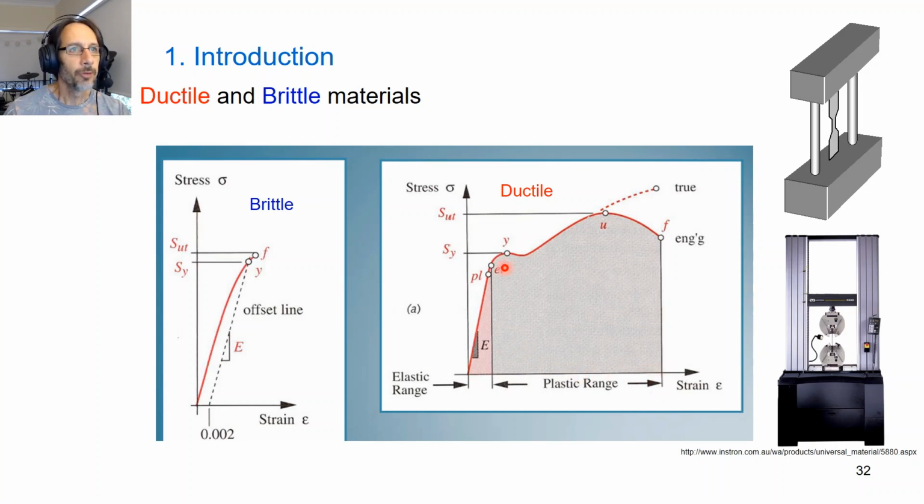So if we have a ductile material, we'll apply the load, it'll stretch, it'll get to this point here where we have the elastic limit. Okay, so here we have a linear elastic region, then we have the elastic limit, then we get to a yield point. So this is for steel, where you have this little drop off. For aluminium, this would just go up and continue to curve up like this. You don't have this little drop after the yield stress here.